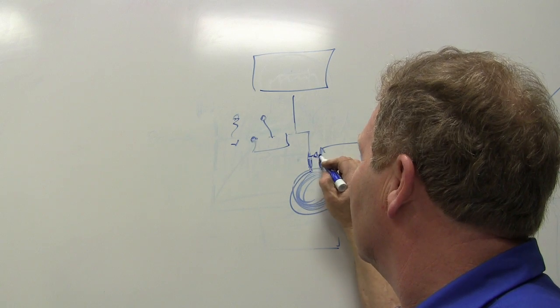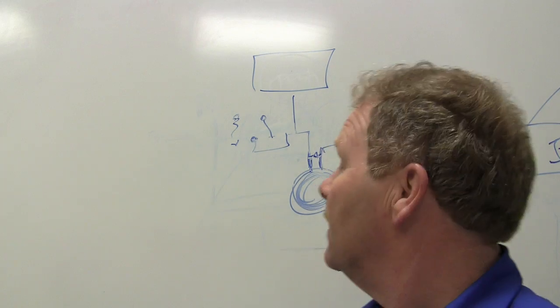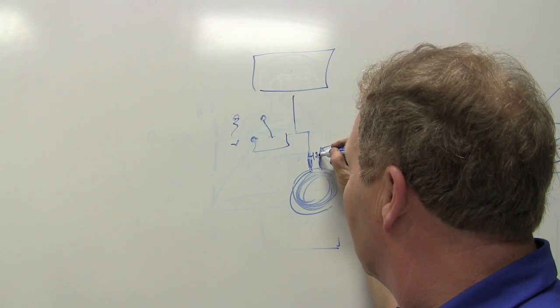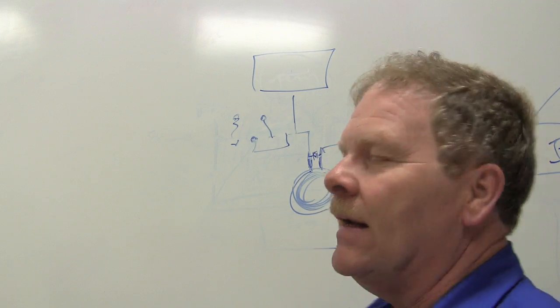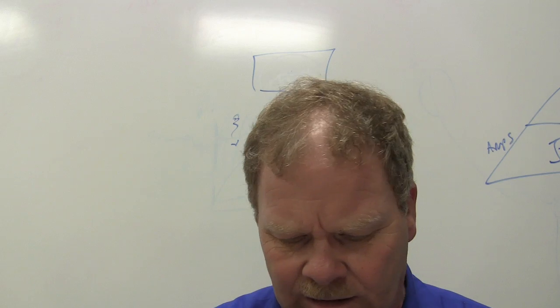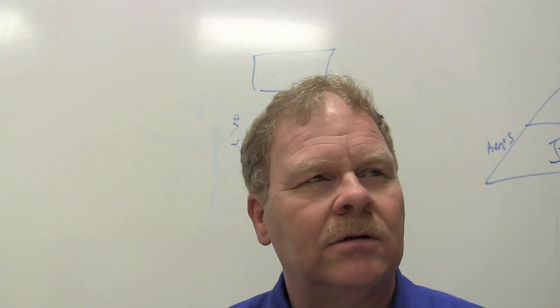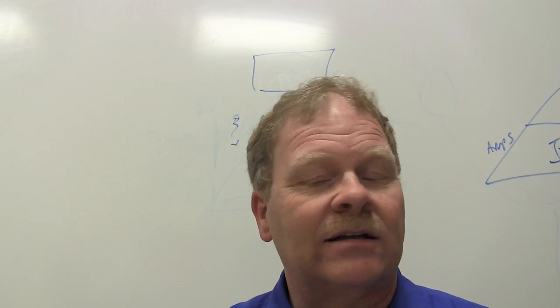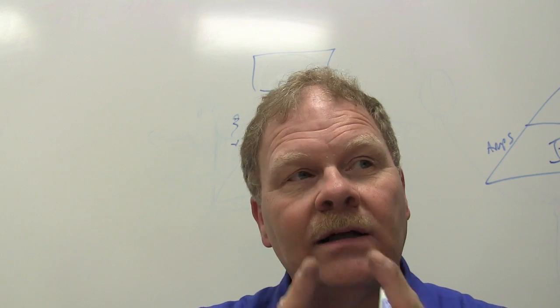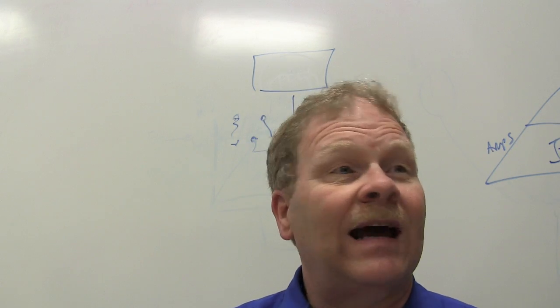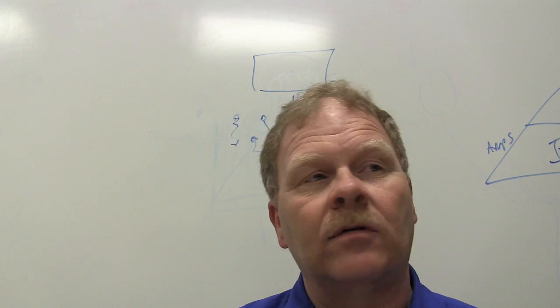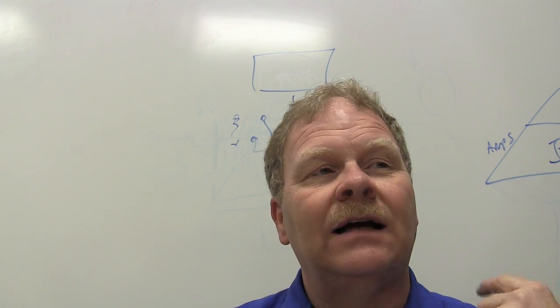See there? You put a little diode right there, and that's called a clamping diode. Every air conditioner compressor clutch has got one of those. It's not built into the clutch, it's in the wire harness. You know what I mean? That has to be there. If somebody ever puts one on there and they don't put that in there, it's going to fry something.